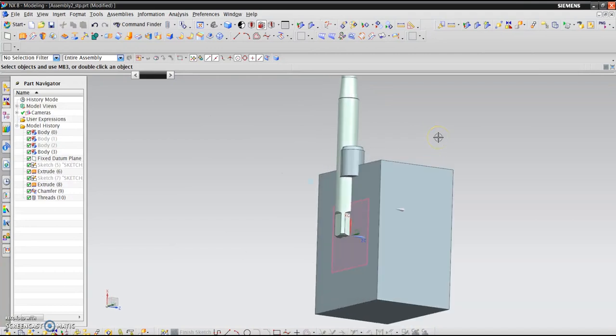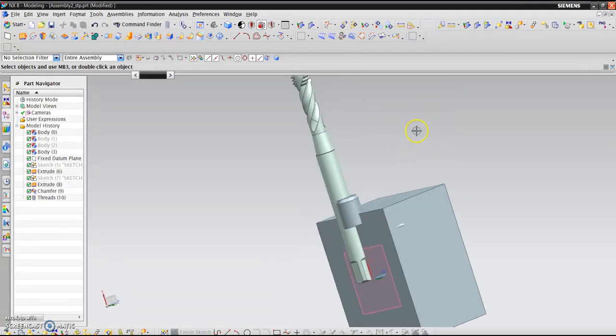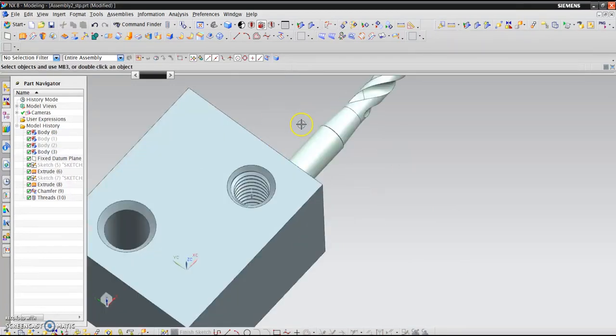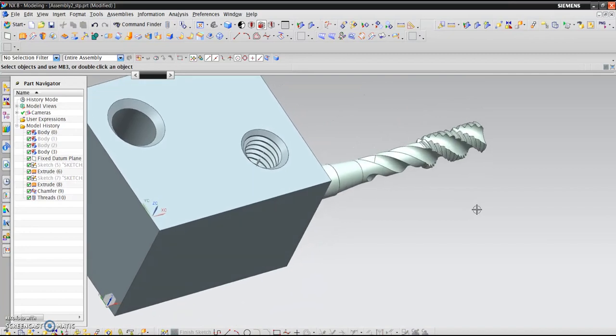So you can see, since it's a through hole, it's not a through hole. I'm sorry guys. Okay, if it's a through hole, you know what tap to use? The best tap to use is a spiral point tap, or you can use a straight flute tap too. With a spiral point tap, the way the flutes are ground and the helix angle is put in, you push the chips ahead during the cut. So if it's a through hole, guess what? You have room for chips to get out of the hole, so nothing will have a devastating effect on the tap itself.